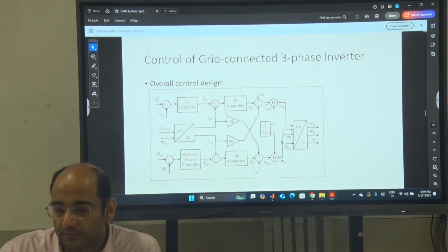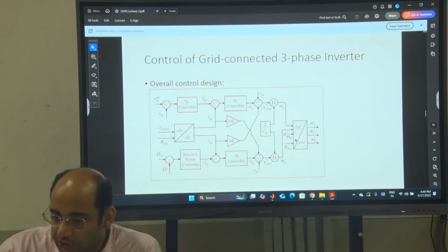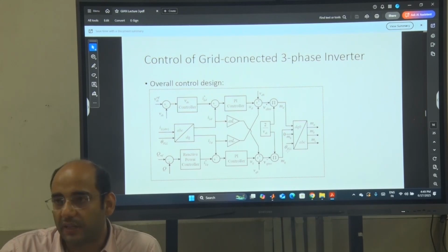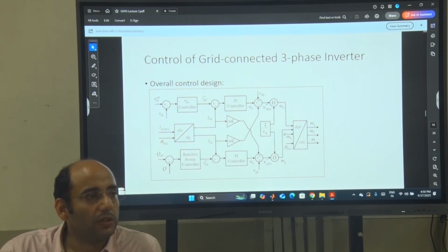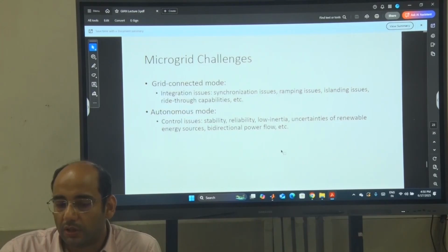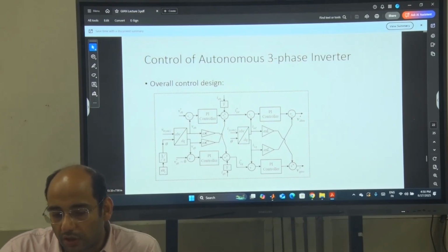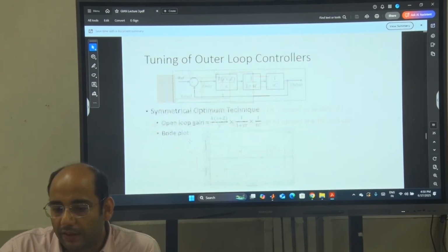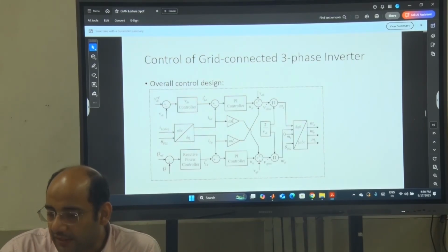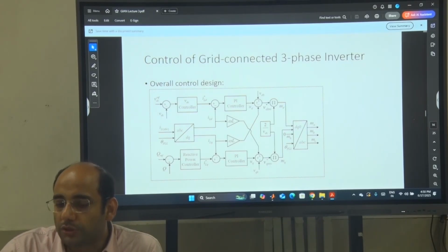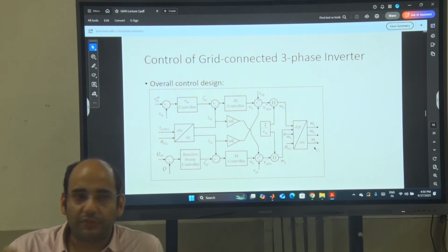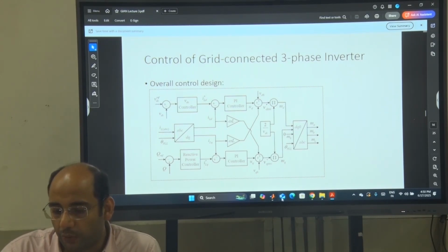You have the D-axis modulation index, the Q-axis modulation index, 0 is your 0, and you give a theta. For autonomous mode, this theta comes from the integration of a constant number, which produces its own theta. That theta you put here as an input to the DQ0 to ABC conversion block. Then you get MA, MB, MC, basically 3-phase reference signals. This is what we are doing here.